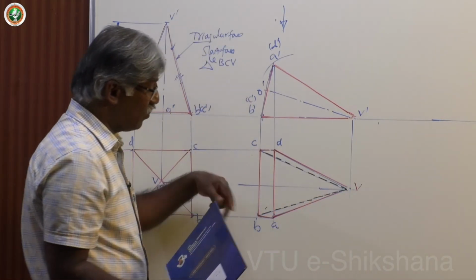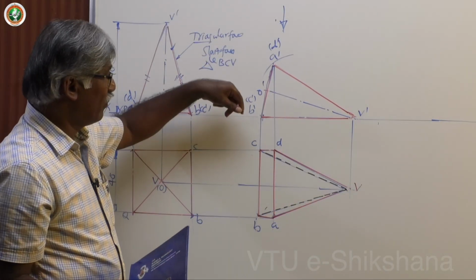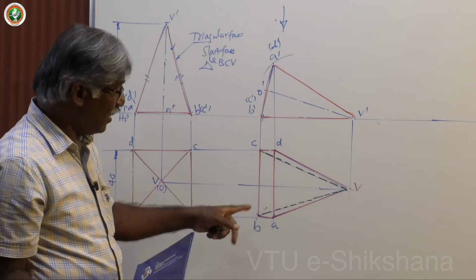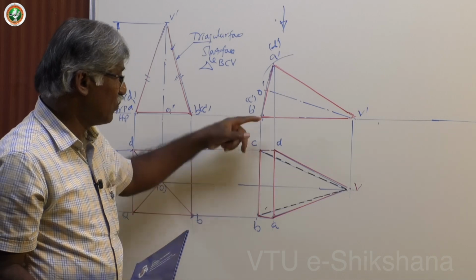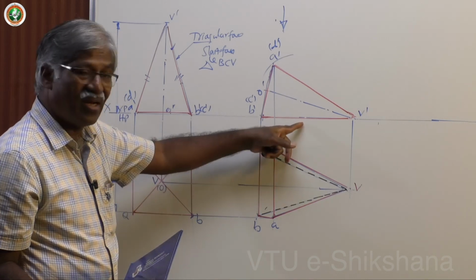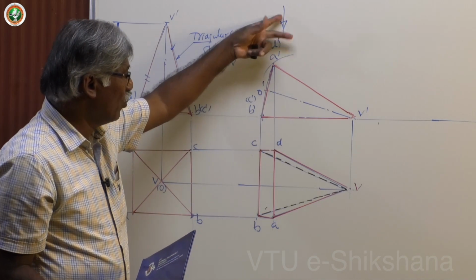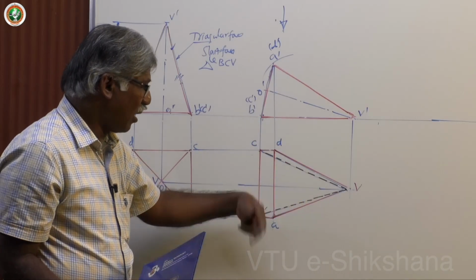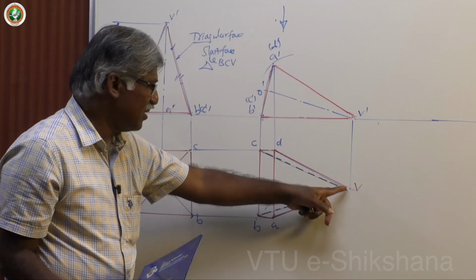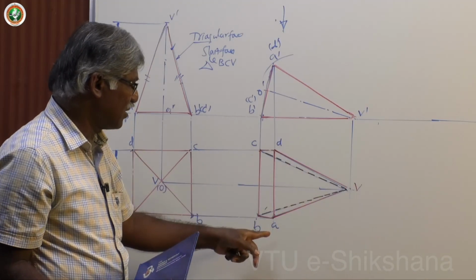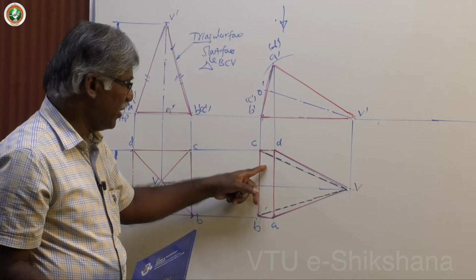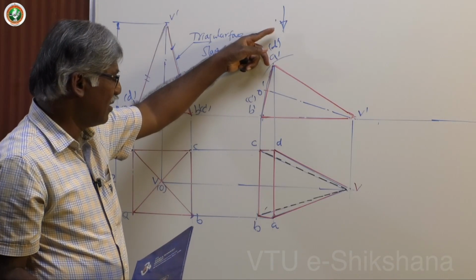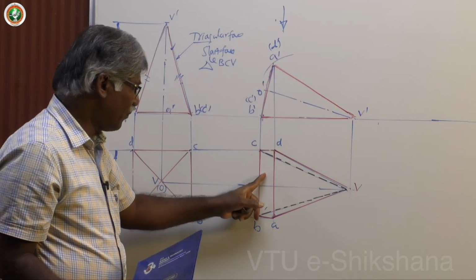Okay. Now, let me go for the farthest point, farthest item. In the previous cases we had a corner or edge, here the surface itself is the farthest item, because it is completely on the ground, all things are above the ground. This particular triangle is dotted. According to that concept, all are dotted lines because these two are also connecting, but they are boundary lines. Okay. Now, the surface is nearer to the observer. Okay. So what exactly is the concept: visible surface, invisible line.